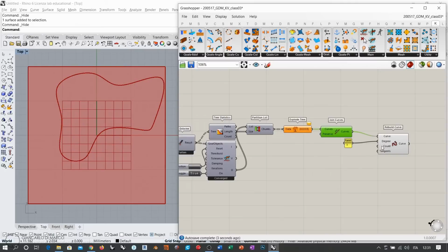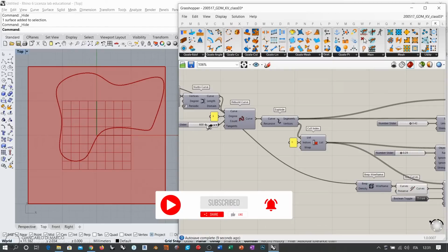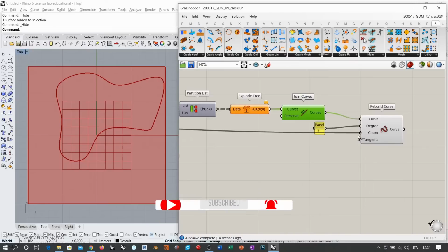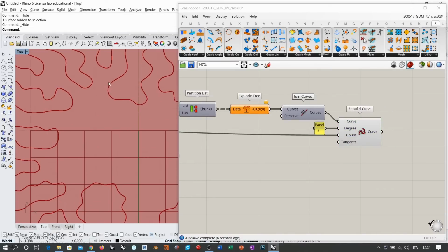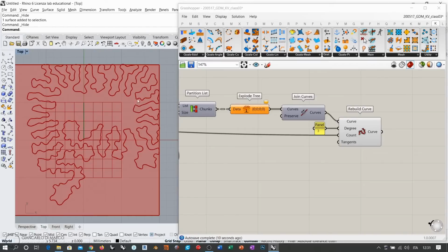And what I'm going to do, I'm going to use as a count, number of control points. Well, we can also use the amount of vertices of the original polyline. This will necessarily give us quite a good representation for our NURBS curve. Now you see that this is starting to give us a smooth curve, but you also see that the smoothness of this curve depends basically on the inclination between two adjacent segments in the polyline.